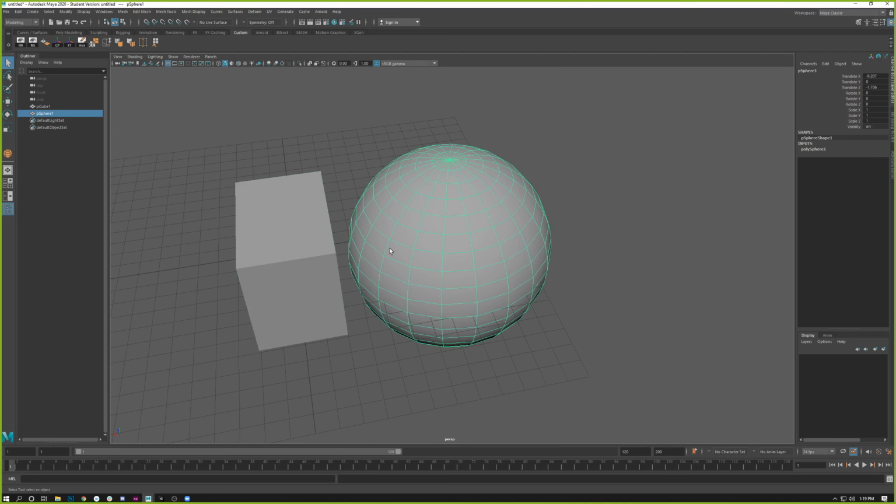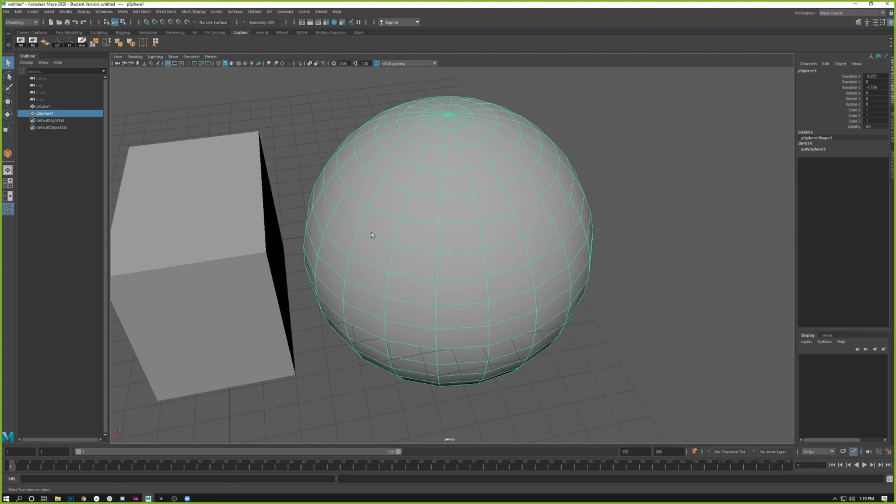But for most 3D software, they prefer quads, so any 4-sided thing, because it lets them subdivide and do certain calculations a little bit easier for a lot of the various tools I show you. So you should strive for quads, 4-sided squares. It's absolutely okay to have triangles, but you should try to avoid 5-sided or more n-sided polygons at all cost.